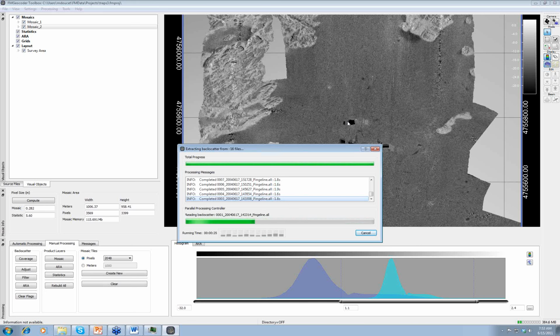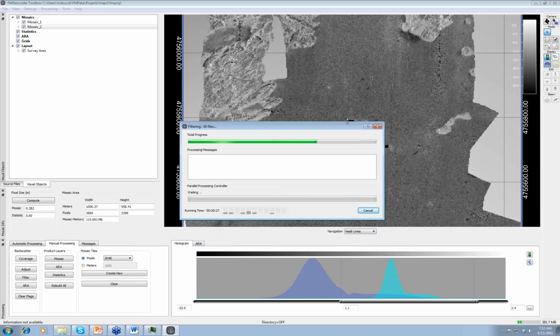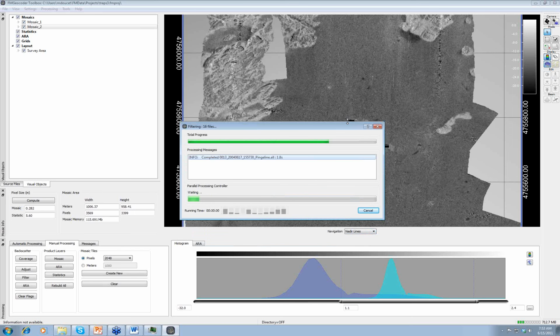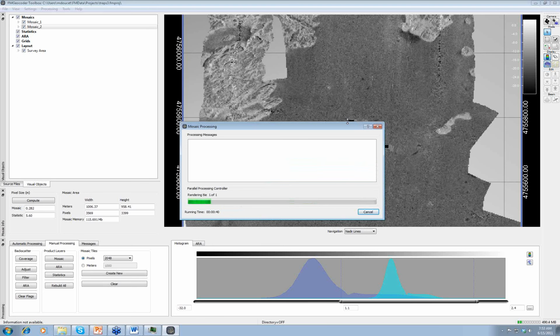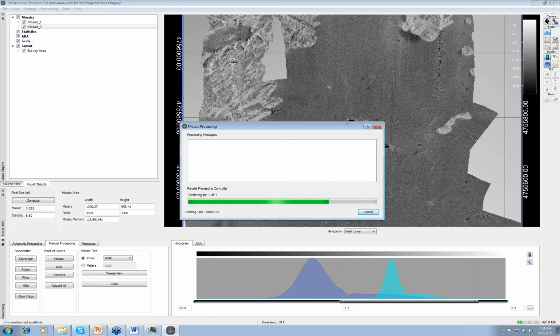So if you've used other tools to edit GSF files, it'll pay attention to those beam flag edits. If you've used a PFM, or if you have a PFM that's been built from .all files, which we can't unload edit flags back to, those edit flags can be extracted directly from the PFM.